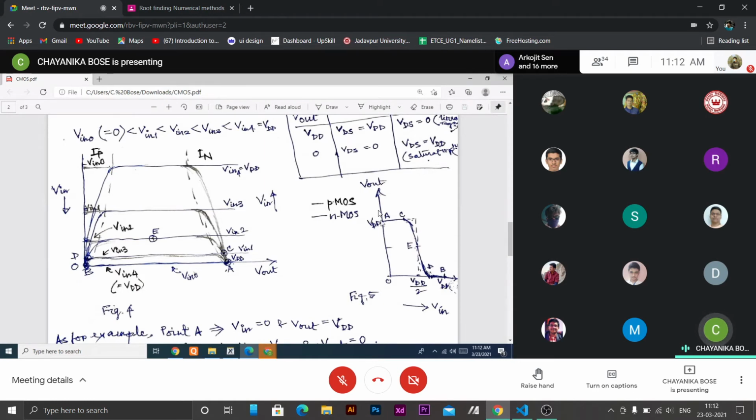That means for this range of input voltage, the output is insensitive to input voltage variation. For 0 input, the output is 10, and it maintains its value of 10 volt so long as the input varies between 0 to 4. For digital operation, we have discrete values of input and output, 0 and 1, 0 and 10 volt. But due to some noise...